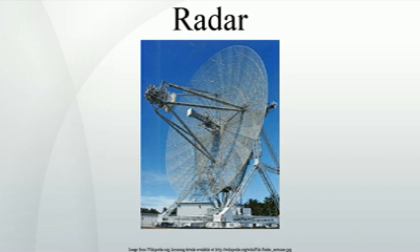Noise is also generated by external sources, most importantly the natural thermal radiation of the background surrounding the target of interest. In modern radar systems, the internal noise is typically about equal to or lower than the external noise. An exception is if the radar is aimed upwards at clear sky, where the scene is so cold that it generates very little thermal noise. The thermal noise is given by kbTB, where T is temperature, B is bandwidth, post-matched filter, and Kb is Boltzmann's constant. There is an appealing intuitive interpretation of this relationship in a radar.